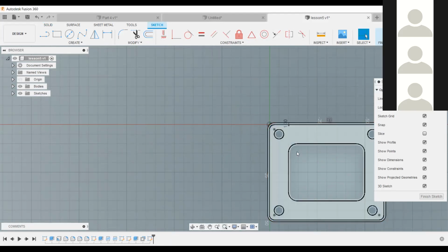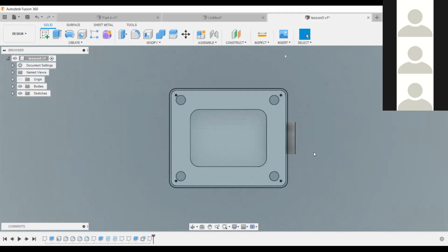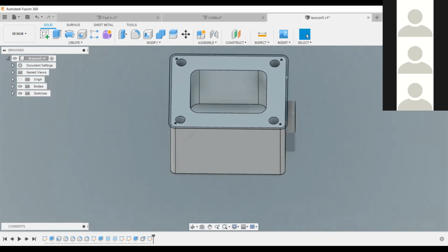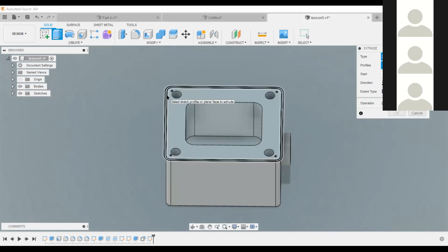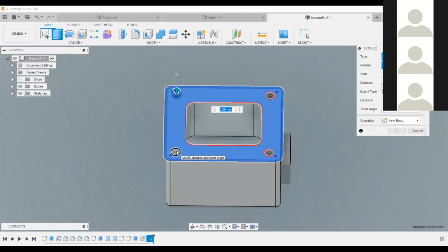So then after offsetting, let me have it at the center. After you offset, you click OK. Then remember you can rotate it. And then now you extrude. While extruding, you click Control, and then you click all these holes, even those holes everywhere, so that when it's extruded it is in solid form.